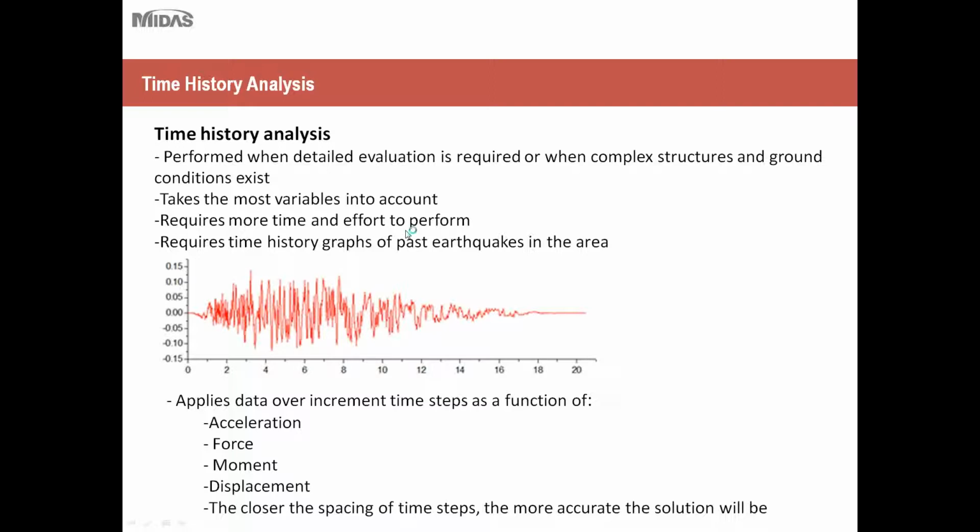That's one of the main things engineers need to consider when deciding between response spectrum and time history analysis: will it be worth the investment? Is this a project that would need this level of detail? Typically, companies that work in seismic regions, or projects located in high seismic regions around California, use time history analysis very regularly, whereas for companies out on the East Coast or the Midwest, response spectrum analysis is the most prevalent.